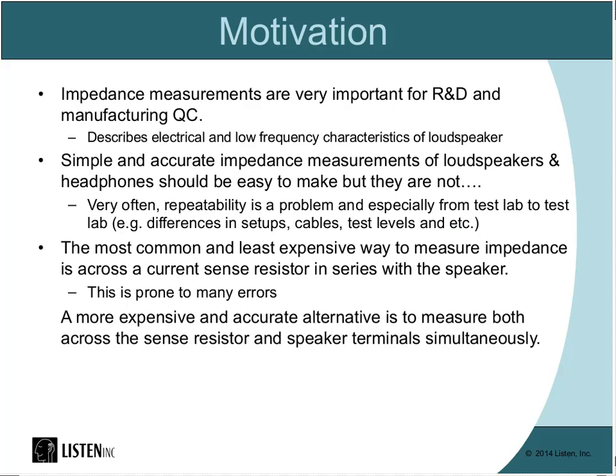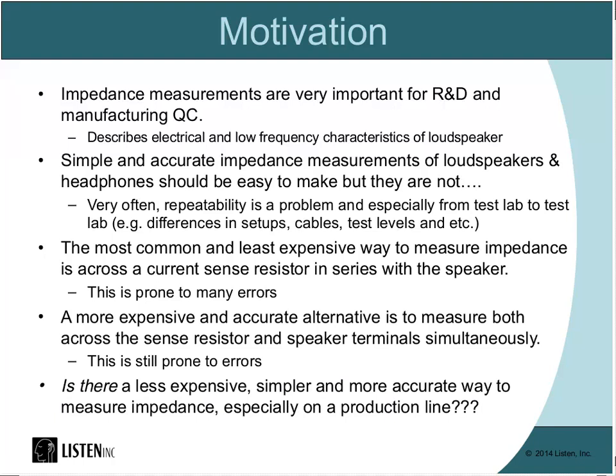There is a more expensive and accurate alternative by measuring both across the sense resistor and the speaker terminal simultaneously. Very often we call this a two-channel method, and I'll show you how that can be done. But there are still some caveats that you've got to look out for in order to make really good, accurate measurements. And then, is there a less expensive, simpler, and more accurate way to measure impedance, especially on a production line? Well, we have some new products that I want to show you that will make this easier.